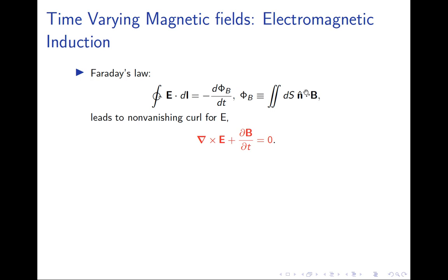So this will be del B del t. And for the curl of E dl on a closed circuit, such as the conductor, you can use Stokes' theorem to convert this loop line integral to the curl of E on the surface which is bounded by this loop. Then you'll get a surface integral on this side and a surface integral on this side.